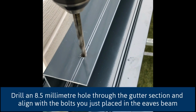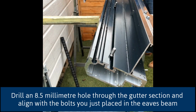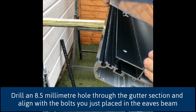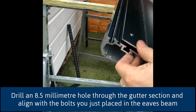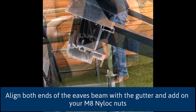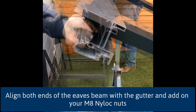Once you've done this, drill an 8.5mm hole through the gutter section and align with the bolts that you just placed in the eaves beam. Align both ends of the eaves beam with the gutter and add on your M8 nylock nuts.